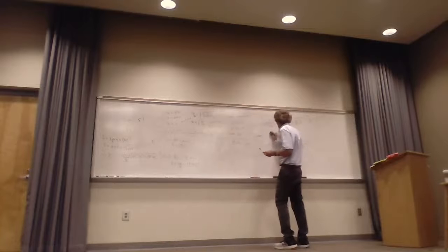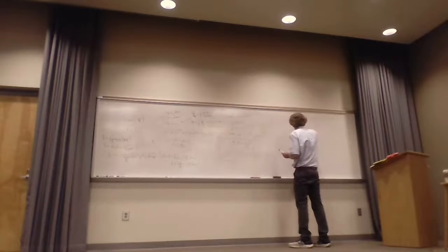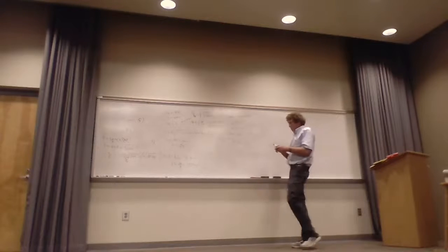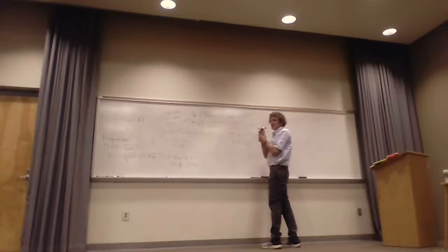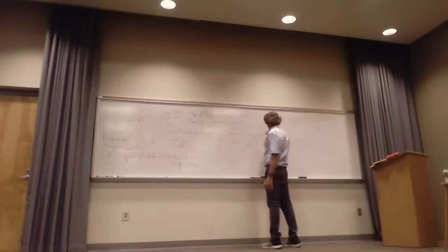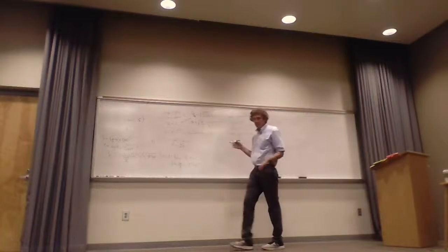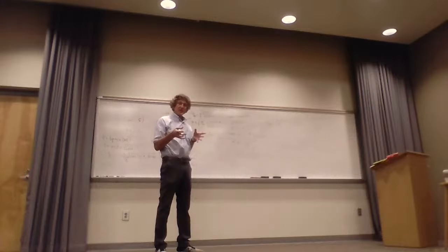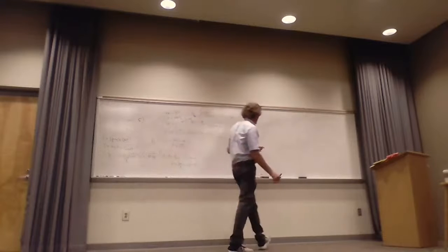Phase velocity. Okay, I like this problem. It goes through everything you need to know and why you need to know it. So what's phase velocity? There's a couple of ways to get it. The easiest way is omega over beta. Think about the cosine waveform. You can always get that because you can take a derivative of the phase, set it equal to 0, and then solve for dz/dt. And what's that going to be?